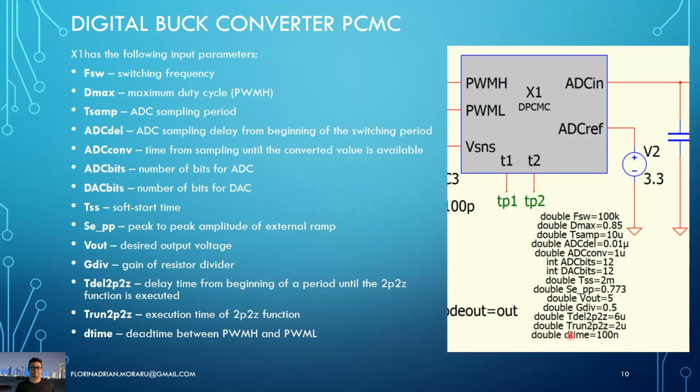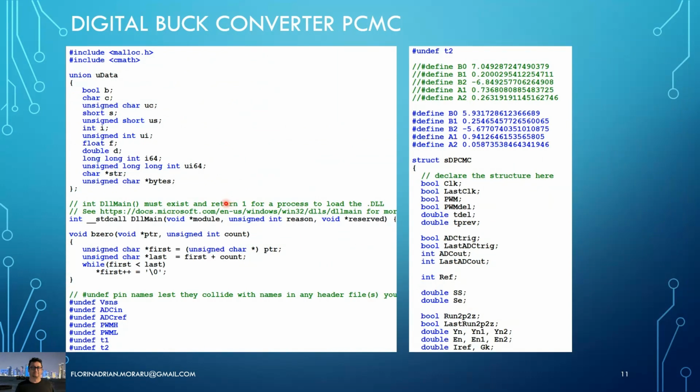And the last input parameter is the dead time. So dead time would be the dead time between PWM high and PWM low.